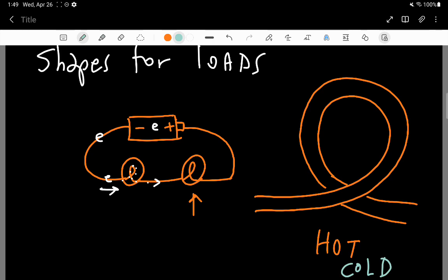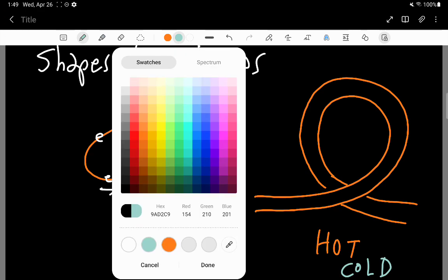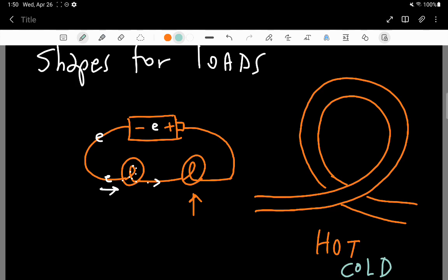Heat cycling can cause changes to the filament or the wire that causes the wire to become more brittle. And so as you heat cycle it and it becomes more and more brittle, what can happen is there can be a place that becomes broken, right? And so the idea is the circuit actually breaks.